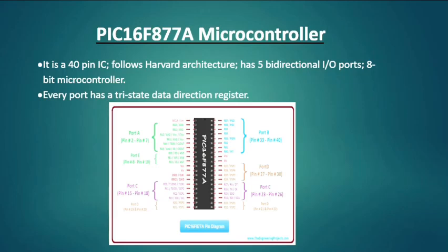So let's come to PIC16F877A microcontroller, which I have used in my project as well. It is a 40-pin IC, follows Harvard architecture, has 5 bidirectional input-output ports, and it is an 8-bit microcontroller. Every port has a tri-state data direction register. So here it's port A, port B, port C, port D, and port E.